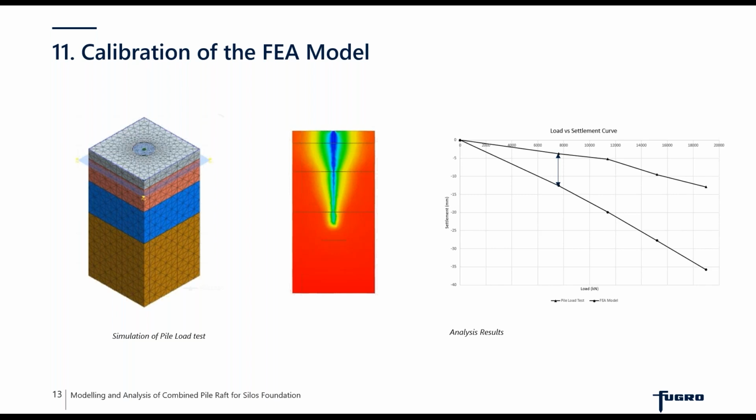So the pile was a 0.9 meter diameter pile. I will detail it out in the coming section. As I said in the previous slide, whenever you have a design profile and a pile with your interface requirement, you should always be able to simulate the behavior of a single pile to check especially the serviceability or the settlement compared to the pile load test.